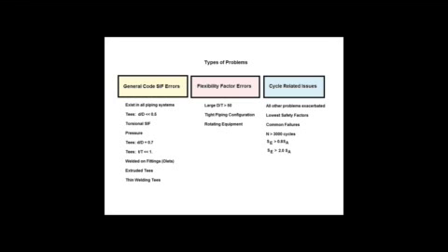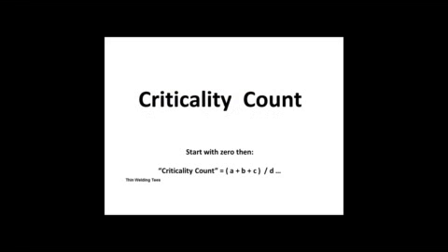We also know that for cyclic services, the safety factors we deal with drop down to a fixed value at about 3,000 cycles. So once we hit 3,000 cycles and have relatively high stresses, we need to be extra careful. And that's a time when a tool like FEA tools can be used more readily. Now, we want to help you define what extra careful means.